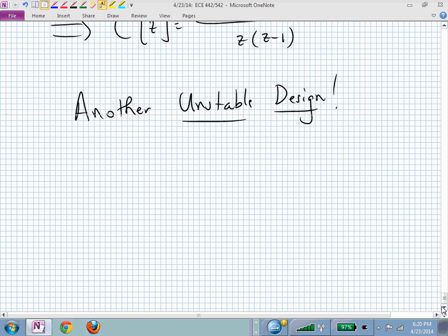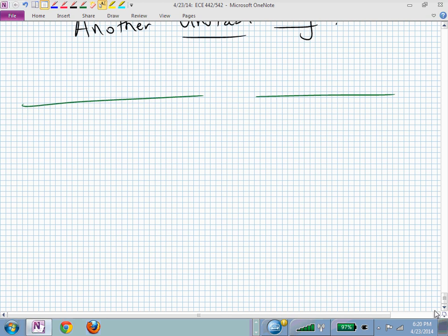What have we tried? Well, maybe we need to think a little bit more open-minded than what I was allowing. We had our unstable pole there, and we said we wanted to do a PID controller because we maybe weren't happy with 350% overshoot, and now we can't seem to stabilize this silly thing with a PID controller, and we thought it'd be better. So now what do we do?